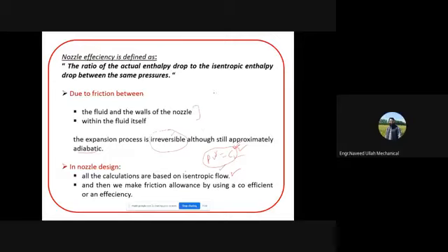Okay, what this means is, for example, considering this isentropic process, if you have the value of a quantity that comes out to be x, based on this assumption that we have an isentropic process. So if there is a deviation from the isentropic process, you can just multiply this with the nozzle efficiency, let's say for example 0.98 or something, or 0.95, etc. So it will give you the exact and precise answer of that particular quantity for which you found the value.